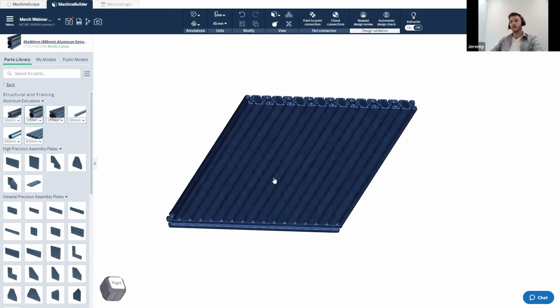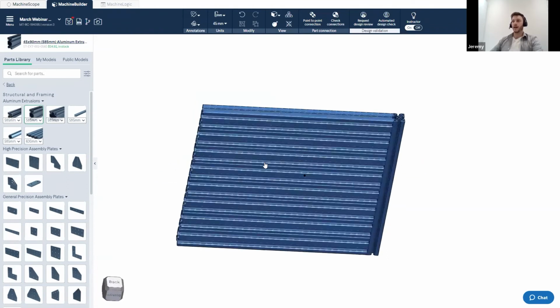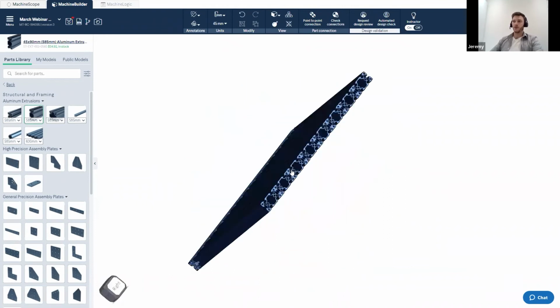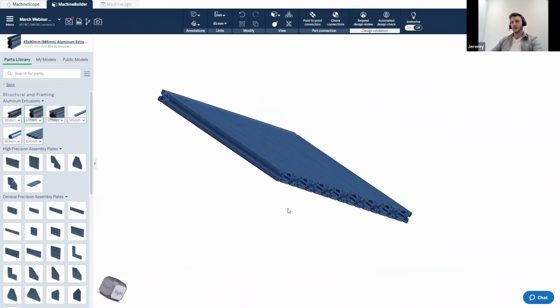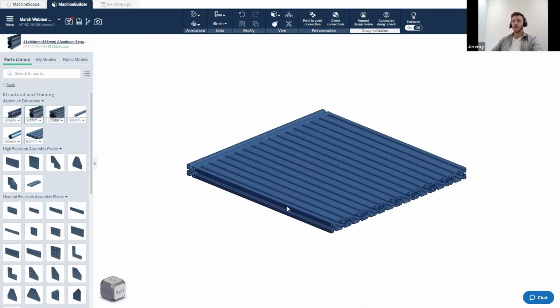From there, another great shortcut that is used quite often by a lot of the application engineers here at Vention is the shortcuts R and F. What these do is they recenter and full screen your design. Say, for example, I'm working and my design is completely upside down at a random angle, and I don't want to have to play around with it too much to get it to the right orientation. I press the R key, which recenters the design in the design space, and F, which will then full screen every part that I have in my design on my window.